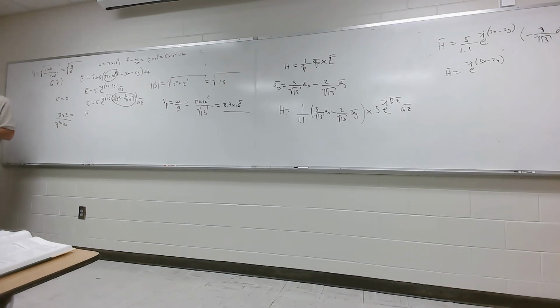Now, I made an assumption that it was non-magnetic, and he made the same assumption, so I can expand on this. I can say eta is equal to the square root of mu naught over epsilon naught times one over the square root of epsilon relative, alright? The reason I can do that is because epsilon is epsilon relative epsilon naught, mu is mu relative mu naught, and if it's non-magnetic, mu relative is one. Now this I know is 125 over the square root of epsilon relative. So we have to find that epsilon relative first. That's how I did it.